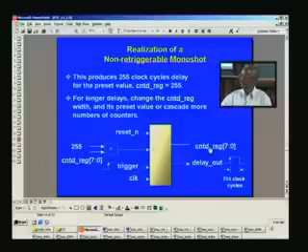And all this triggering will be done at the positive edge, the rising edge of the trigger, and the clock is also there. Once again, all transactions take place at the positive edge of the clock. When the counter register equals 255, this will be activated and this will be reset, and that is how you get a delay of 255 seconds. We will see the waveform so as to get a better grasp. So now we will have a look at the waveform.